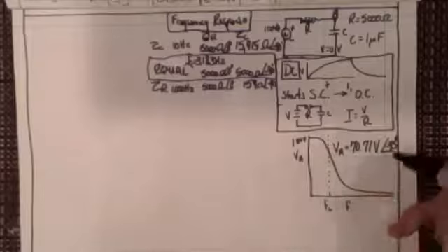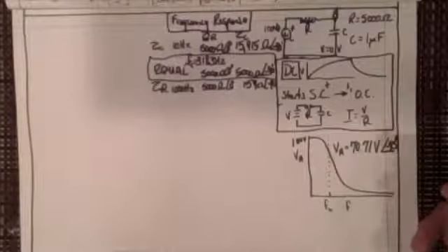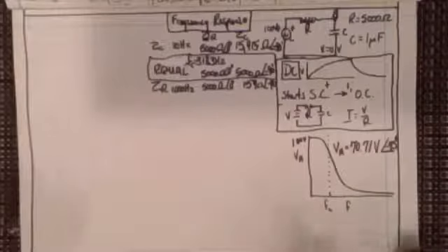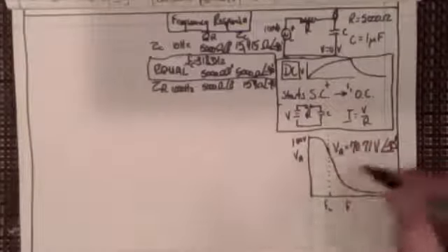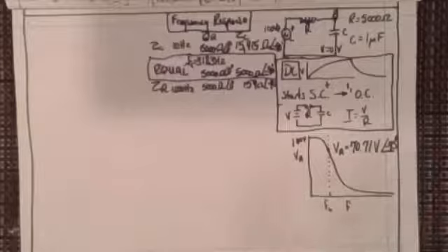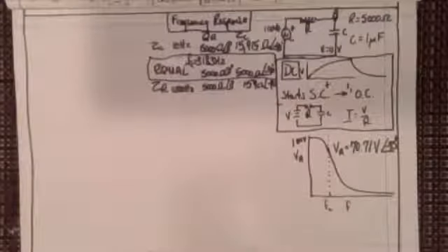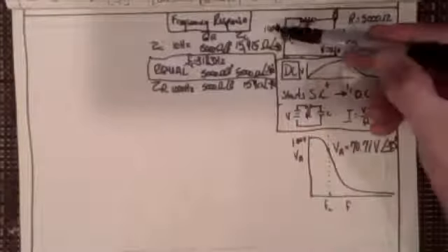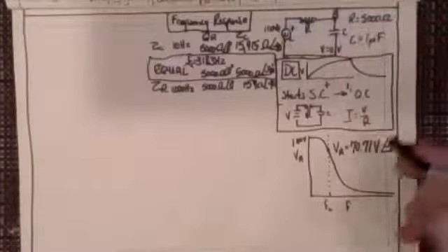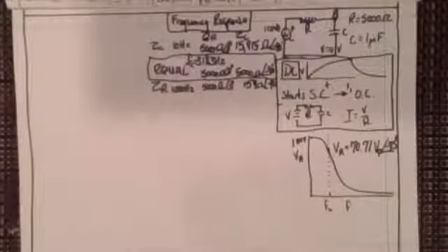voltage is. Now that voltage is very special, by the way. I don't know if I want to get off track here right now, but this voltage with a 70.71, of course, you know that that's 1 over the square root of 2 times the source voltage, which is 100 volts peak, right? So this is still volts peak that I'm talking about here. It's not RMS.